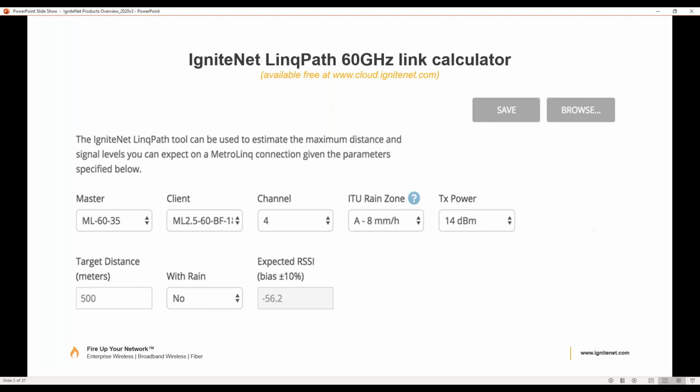If you're slightly below 60 gigahertz, or if you go above 60 gigahertz, channel 3 and 4, you actually have a better, or I should say, a different signal strength depending on what channel you're on. A couple dB plus or minus. So that's actually a factor which is kind of unique to 60. It depends on what channel you're on. The signal actually is a little different.